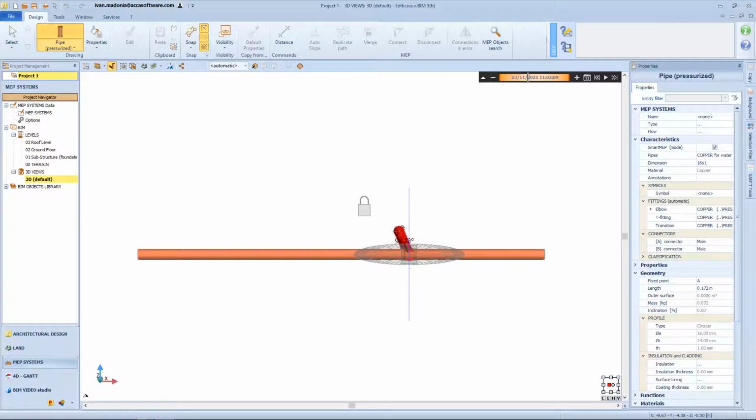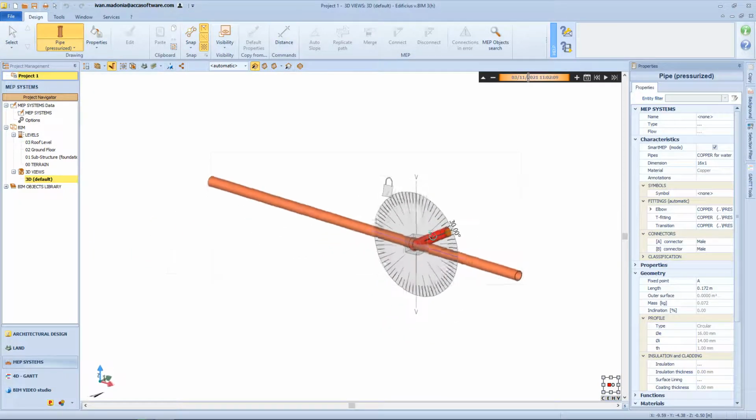Thus appears the protractor positioned by default in the plane of the main pipe that allows you to choose the direction of the branch of the fitting, as seen in the modeling of the pipes. If, on the other hand, you want to trace the pipe on a horizontal plane, or vertical planes in the local reference, you can always use the directional cube. Unlike curves, for this type of fittings, it is possible to orient the branch according to any angle.